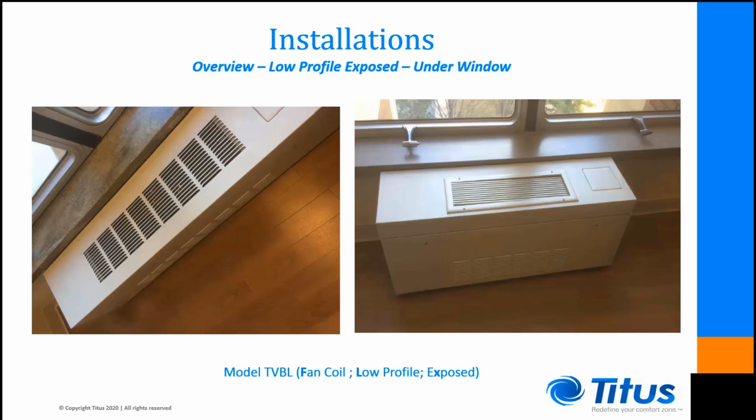In these two photos, we can see examples of the low-profile console unit installation. These two projects utilize tall windows and come fairly close to the ground and do not leave enough room for a full-height console unit. In addition, there wasn't space for the unit to be installed behind a project-provided custom cabinet, so the exposed painted-style low-profile units are used as they will be seen in the occupied space. We can also see that the unit on the left has stamped supply louvers while the unit on the right has a discharge grill.